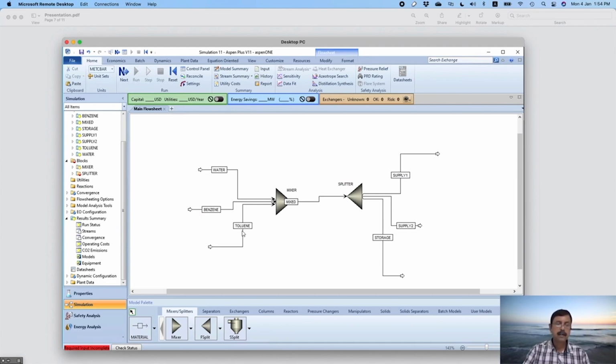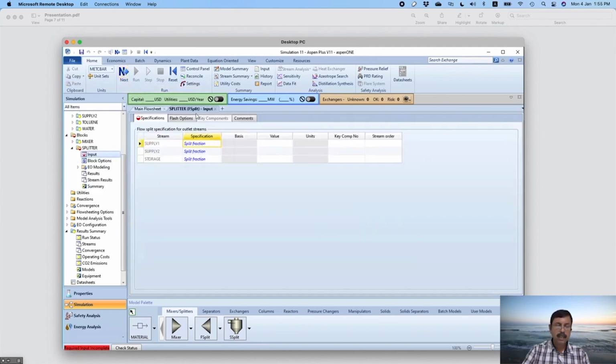Here, let us see what are the options they are asking for splitter, F split. So F split, all the lines are together and they are asking for a lot more options other than split fraction and flow. So they have limit flow, volumetric limit flow, cumulative limit flow, cumulative volumetric limit flow, and residual action. Now these two already you know.